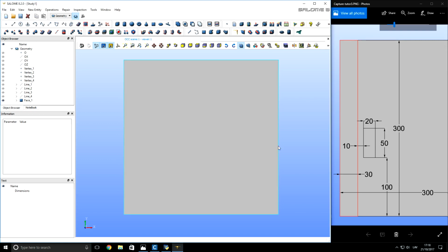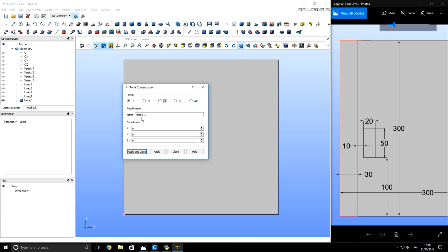So the next step now is going to be to create this billet and copper inductor. To create a billet, what we need to do is just split this computational domain in 2 parts, and we will do it with line. But first, to create a line, we have to create points. So first point will be at x equal to 30. Because 30 millimeters is radius of our billet. We click apply. Then we will change y to 300 because 300 millimeters is height of our computational domain. We click apply and close.